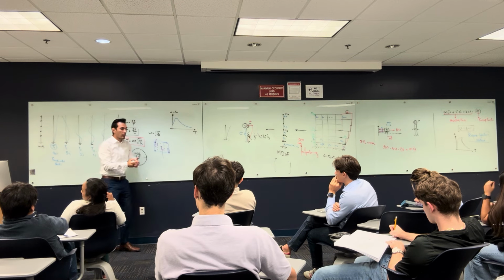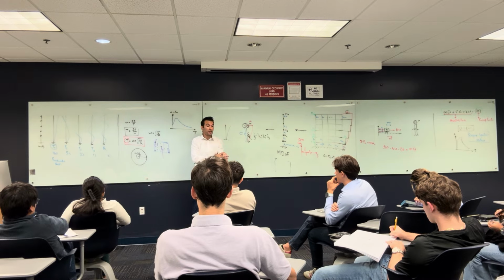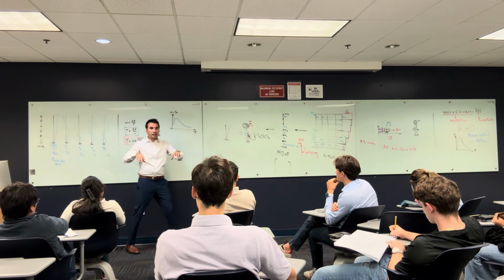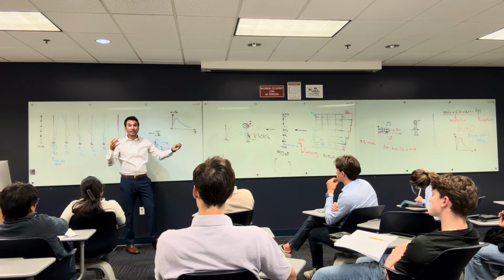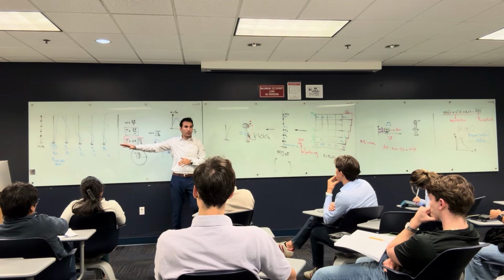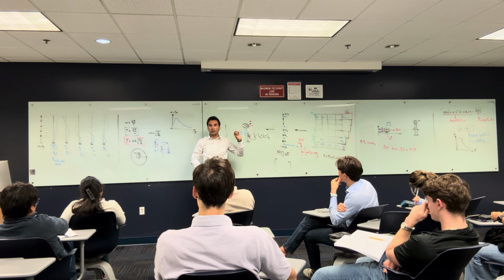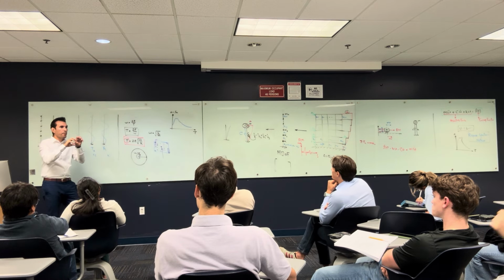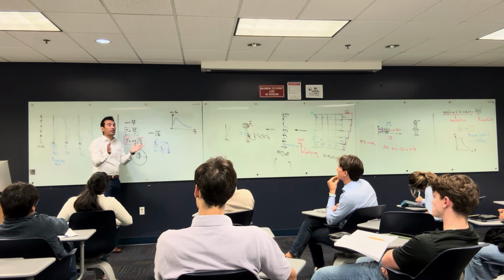And let's say you have a tall building and a small building. This small building is going to have one period, and this tall building is going to have a different period. Even if you have two similar structures in the same construction zone, the same buildings, you are not sure that the environment of construction of this building was the same as here. Let's say you did a concrete element in this structure and a concrete element in this structure, but in one of them the concrete wasn't that good. Sometimes when you pour concrete, you have some holes, some nesting happens. So elements are not going to be the same. Soil is not going to be the same. Everything might not be the same.